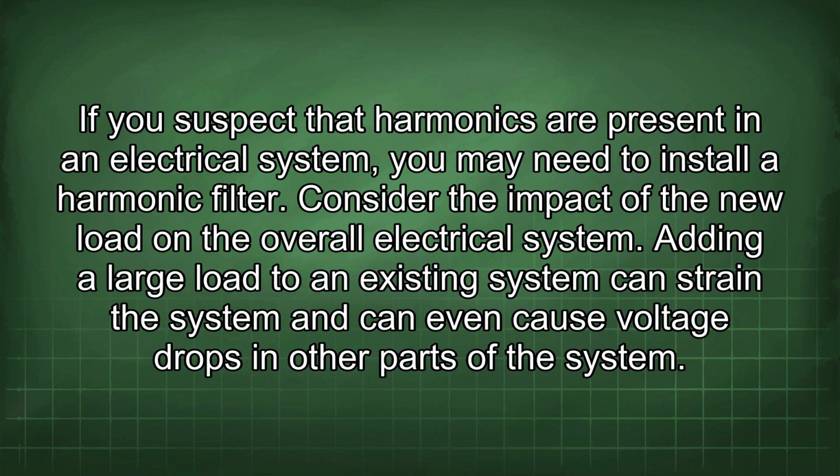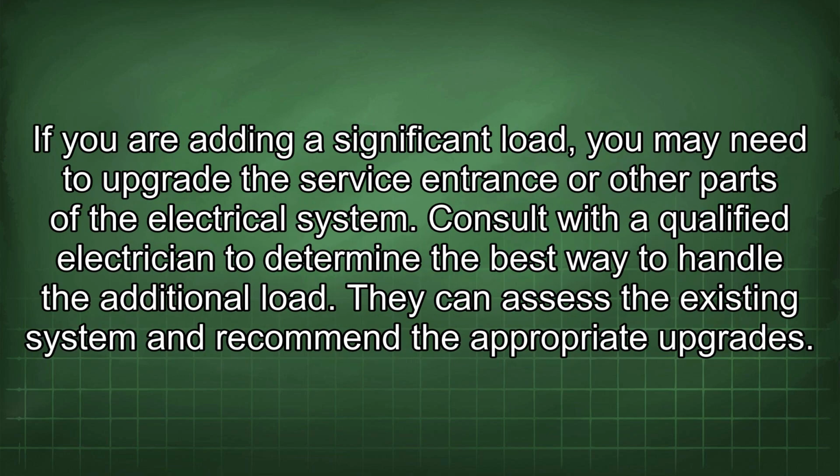Consider the impact of the new load on the overall electrical system. Adding a large load to an existing system can strain the system and can even cause voltage drops in other parts of the system. If you are adding a significant load, you may need to upgrade the service entrance or other parts of the electrical system. Consult with a qualified electrician to determine the best way to handle the additional load. They can assess the existing system and recommend the appropriate upgrades.